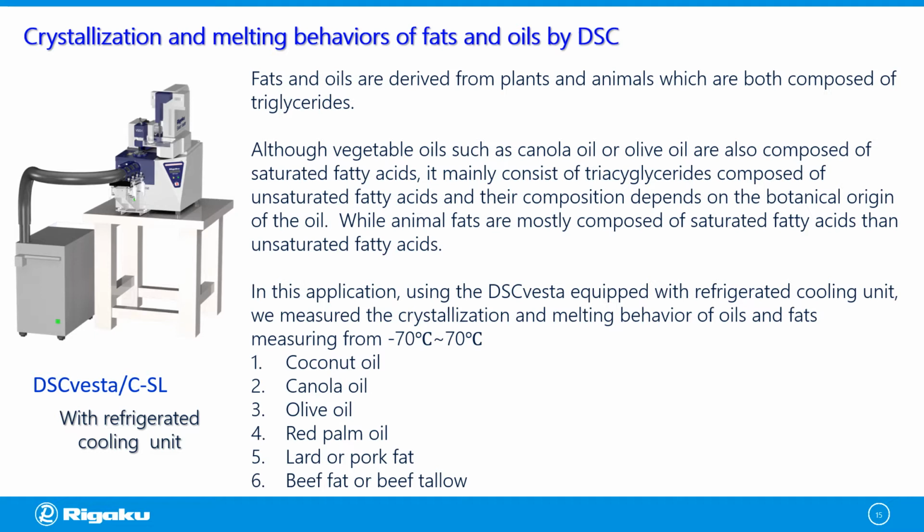In this application, using the DSC Vesta equipped with refrigerated cooling unit, we measured the crystallization and melting behavior of oils and fats, measuring from minus 70 degrees centigrade up to 70 degrees centigrade. We measured coconut oil, canola oil, olive oil, red palm oil, lard or pork fat, and beef fat or beef tallow.